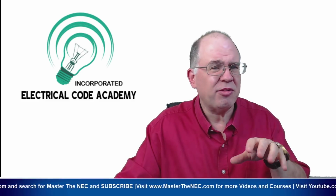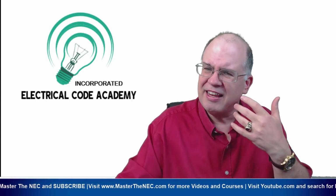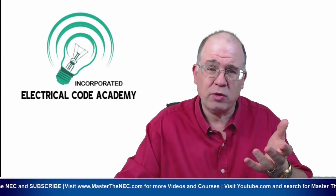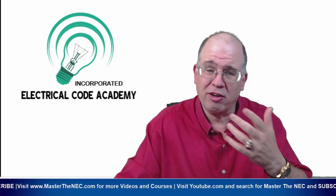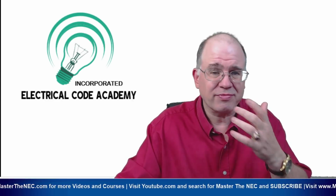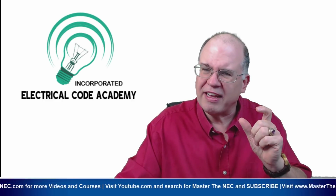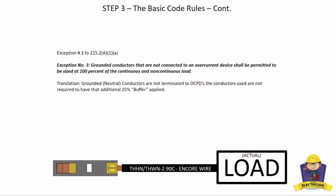But it's saying when it comes to the grounded conductor, since it's not at one of these overcurrent devices, it's not a limiting factor, it's not attached to it. So I can just take it at 100%. I mean, the load is the load. I could take 100% of the continuous load and 100% of the non-continuous load, and I'd be perfectly fine. So that's an exception that allows you to do that for the grounded neutral conductor. Okay. Let's get back to the presentation.